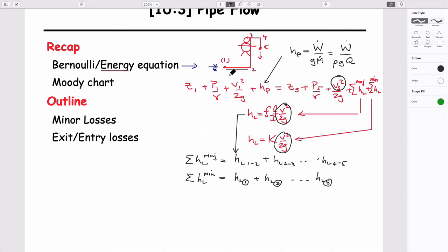And so in this, I suppose the pump would be sitting here, and that would be added into this equation on the left-hand side. So you have enough to be able to do this. So for instance, in this particular case, we'd be able to define all these components. We'd know exactly what the velocity we'd want coming out of the system at the end would be, and therefore, if, for instance, the pipe diameters were all the same through here, the velocities by continuity would be the same throughout, and we'd know what those velocities would be to be able to calculate the head losses.